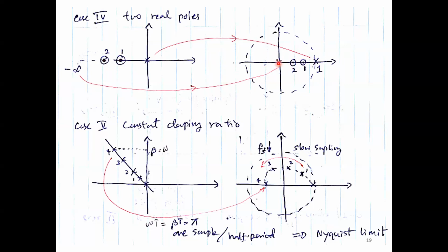So the overdamped response of a second order plant will look something like this in continuous time. And in discrete time, it will be like this, 2 poles on the real axis between the origin and 1, 0. Okay, please remember this. This transformation is highly complicated, so it is very difficult to visualize. So the best way going forward is to figure out specific cases, like pole at 0, pole at infinity, or pure oscillatory poles, and figure out their corresponding positions in the Z plane.